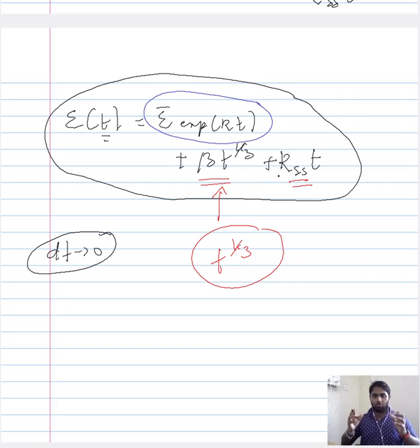So even though outwardly it takes a phenomenological approach, the ultimate expression is an overall expression that is not confined to a specific stage. This expression generally categorizes the overall creep into two stages: there is an exponential increase in strain with time, and finally there is a constant increase in strain over a period of time, and subsequently you arrive at this expression.